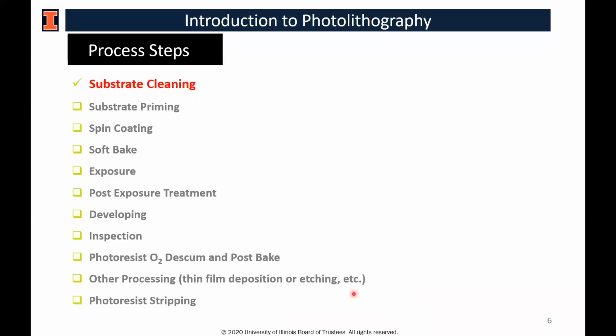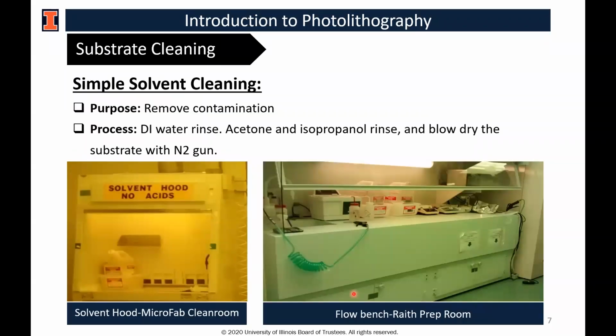Here is the complete list of process steps. Let's just start with substrate cleaning. The purpose of a substrate cleaning is simple, just to remove the contamination. And when you open a box of wafers, no matter how clean they look, you still need to clean it. We just run a simple cleaning process here.